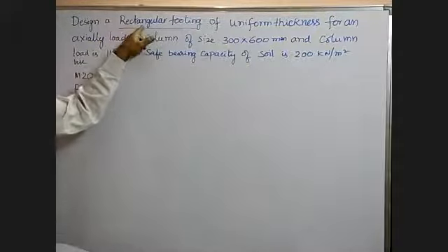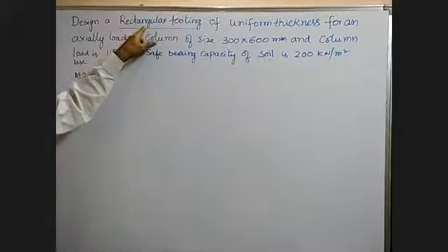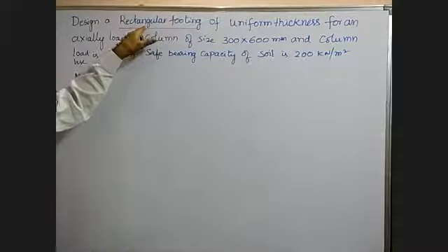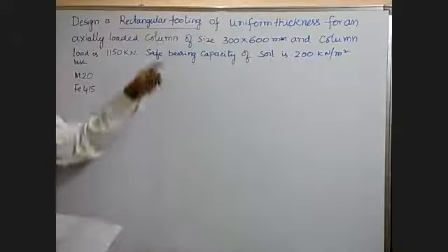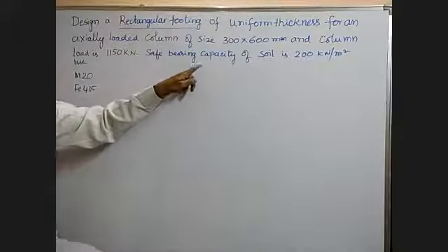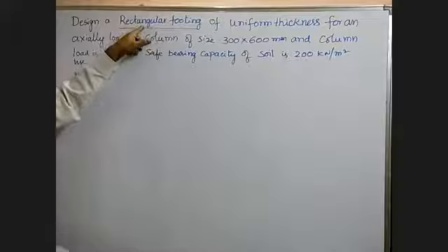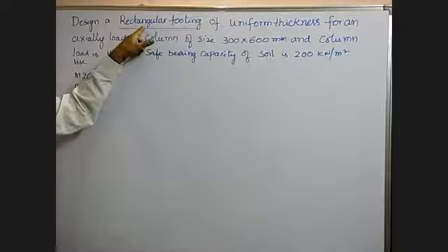That means the shape of the footing, whether it is a square footing or rectangular footing, better always go for square footing if it is not mentioned. Here in this problem, it is particularly mentioned that it is a rectangular footing. So there is no choice, you have to go for rectangular footing.